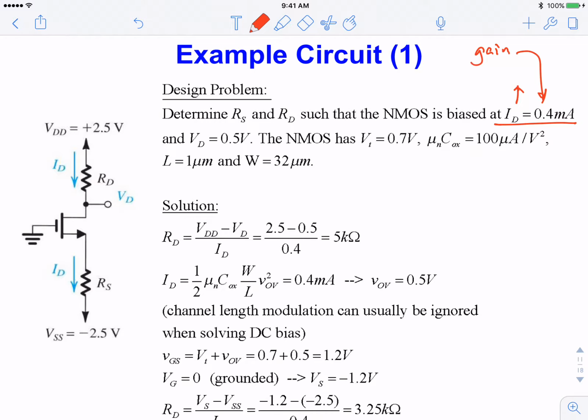So usually we design a circuit. We want to design the steady state current flowing through the drain. And we can also specify what the steady state voltage is, 0.5 volt. And the transistor we have usually comes from the technology that you are designing your circuit in. Let's say you are using a transistor provided by TSMC, one of the foundries. You are using a 40 nanometer technology, so you will be given the transistor characteristics, kind of like a data sheet.